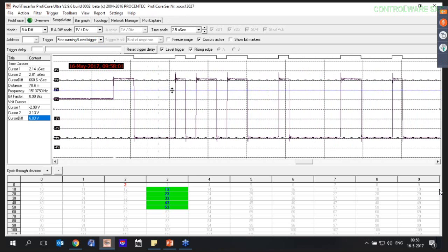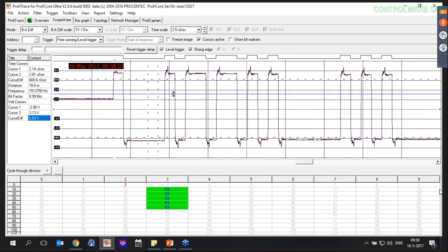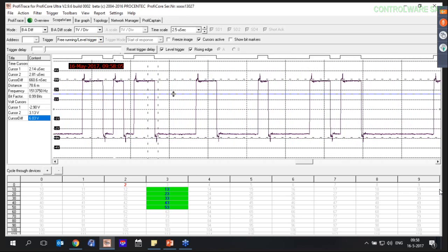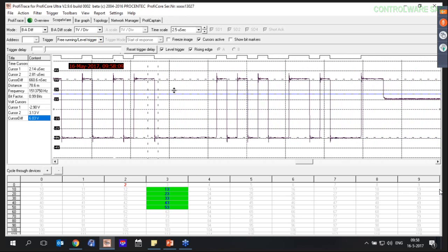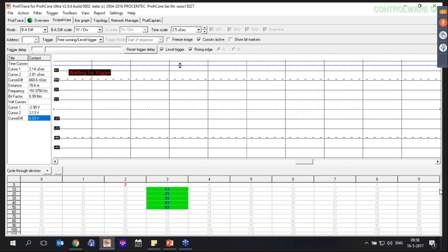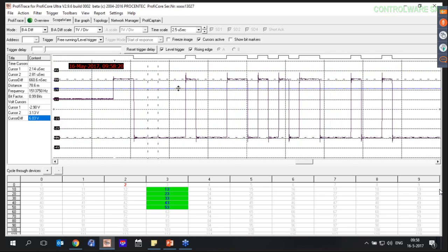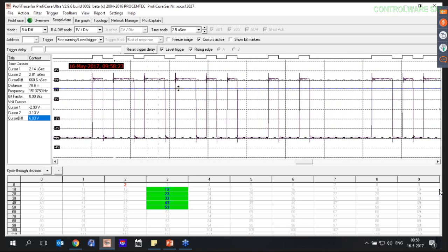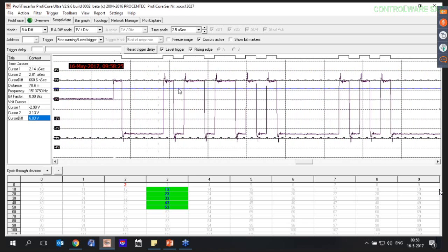When something goes through this line, then my program will trigger on this message. So if I set this line a little bit higher than my signal, like that, there's no signal showing on your screen. With this level trigger, it's easy to measure EMC problems.